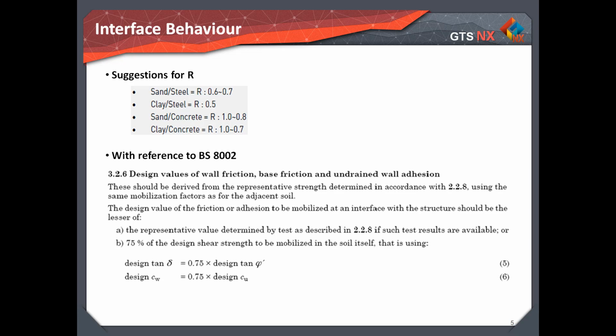The general strength reduction factors for structural members and neighboring ground properties are as follows. Checking the element size considerations calculates the interface material properties considering the average length, average area, and so on, of the neighboring ground element when creating an interface. In other words, the average length and average area are multiplied by the virtual thickness in the equation below to calculate the tangent and normal direction stiffness of the interface.